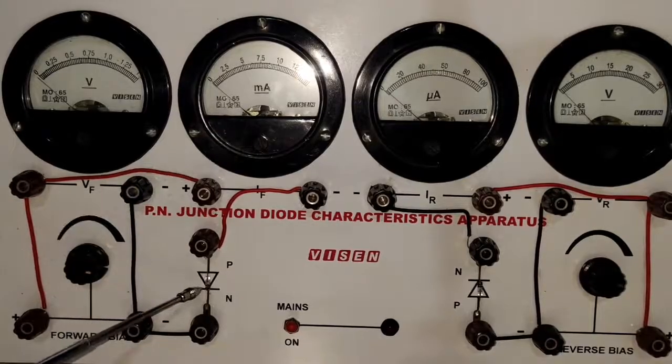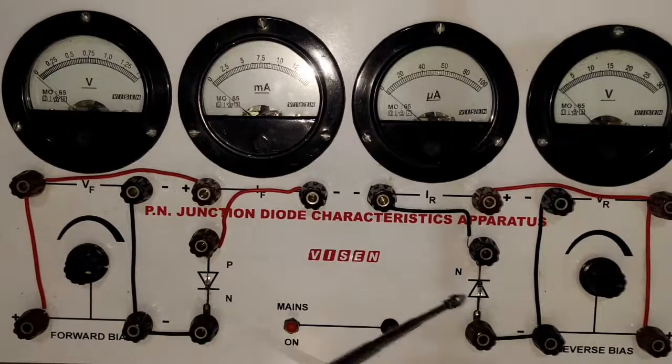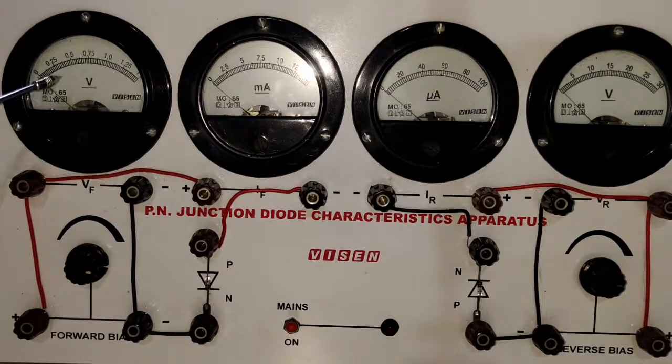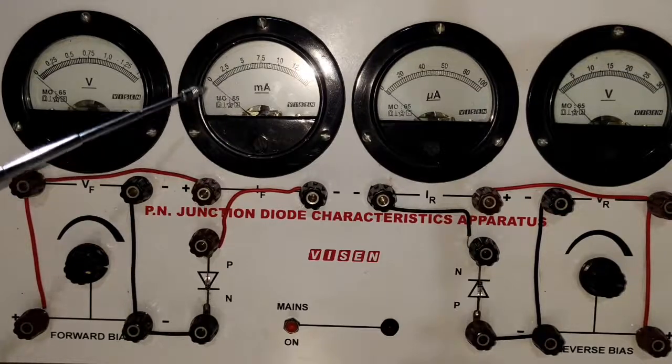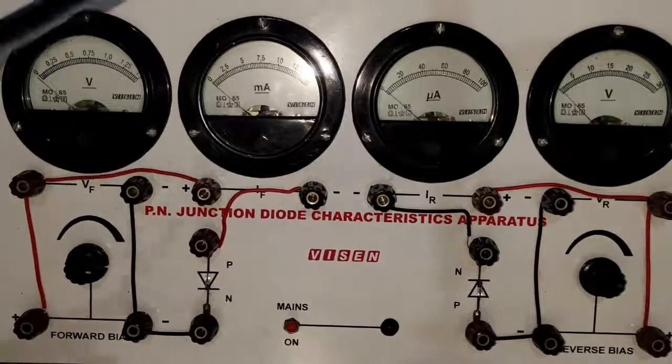So this is the diode. We are studying the characteristics of this diode in forward bias as well as in reverse bias. For forward bias, you see that the voltmeter is of lesser range and the ammeter is of more range because more current flows due to the majority charge carriers. And in reverse bias, you